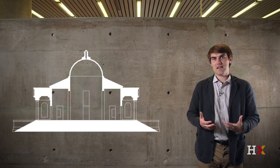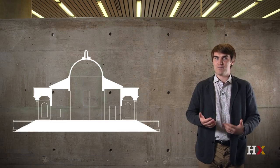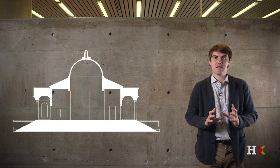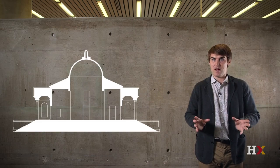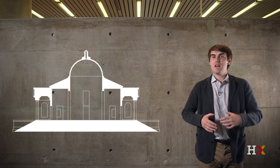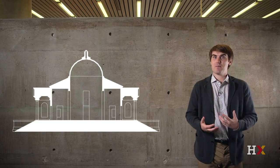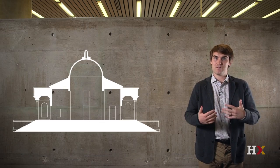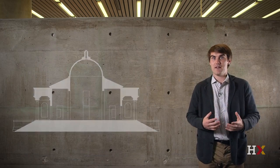In general, you will cut a section on the most important axis of the building. So in this case with the Villa Rotonda, we've cut it right through the middle. So you can see the different symmetries and massings that are at play, and how the peripheral spaces relate to the main central space. If you really want to properly describe a building, it will take several sections to show us how the different spaces relate in the major areas, the minor areas, etc.